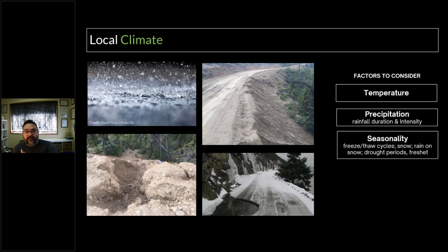You have to consider these through the whole life cycle, right from planning through deactivation. So that's things like construction season. When can I start to build and how long do I have? That's going to impact your planning of start dates or even length of construction for areas with very short seasons. Again, important to understand at the planning stage.